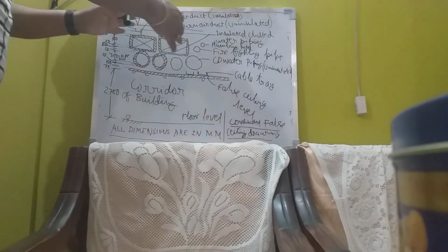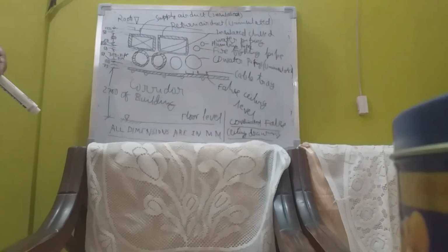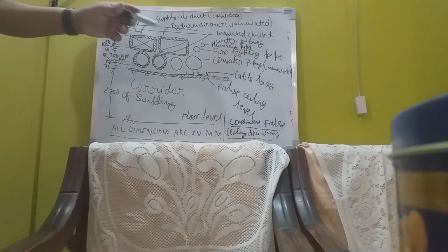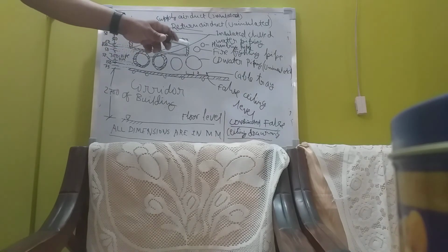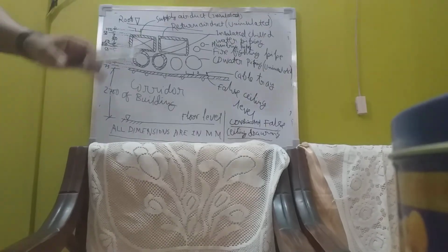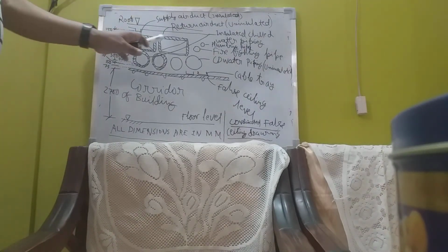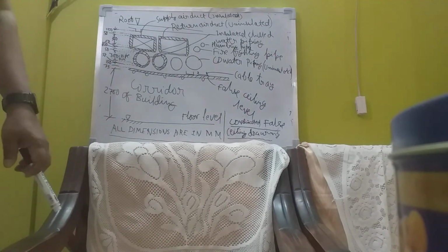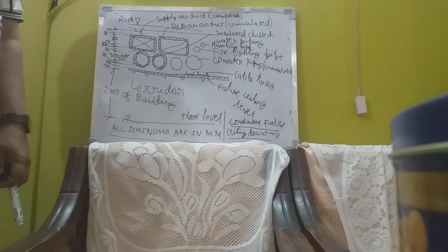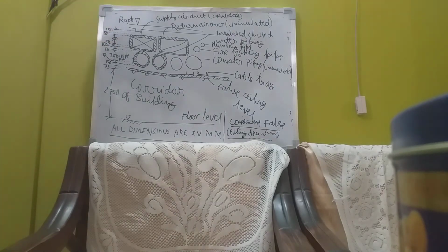So see, you have restrictions everywhere, but the architect will always tell you to put these diagrams having the maximum duct flattening, and you have to tell the point, sir, this is 1:8 now, and I cannot further flatten the duct. I cannot flatten. That's all. You have to put your foot down at a certain point. I think it is clear.